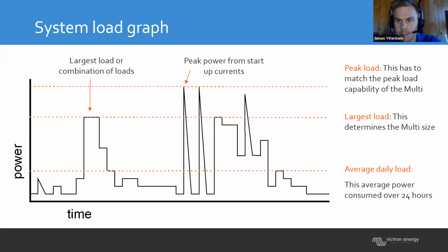This is a way to try to figure out what size peak loads. This can be startups on an inductive load, or let's say an air conditioner or anything that's got a high startup power. The peak of the inverter needs to be within the power requirements, so we're not overloading the inverter. For the first one, you can just look at the biggest startup power and then add a little cushion.